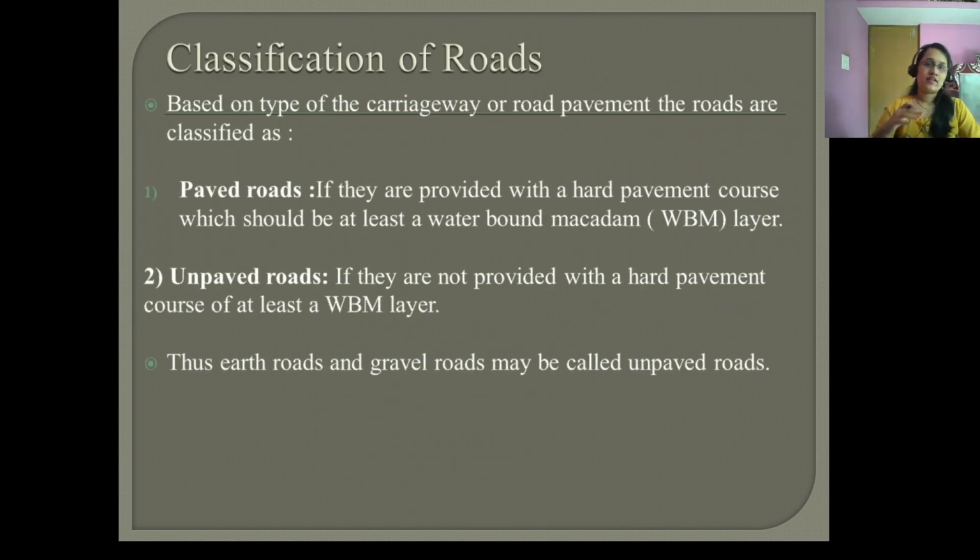Coming to the next classification, roads are also classified as paved roads and unpaved roads. How do you define a paved road? If they are provided with a hard pavement course, which is at least a water-bound macadam layer or WBM layer. What is a WBM layer?